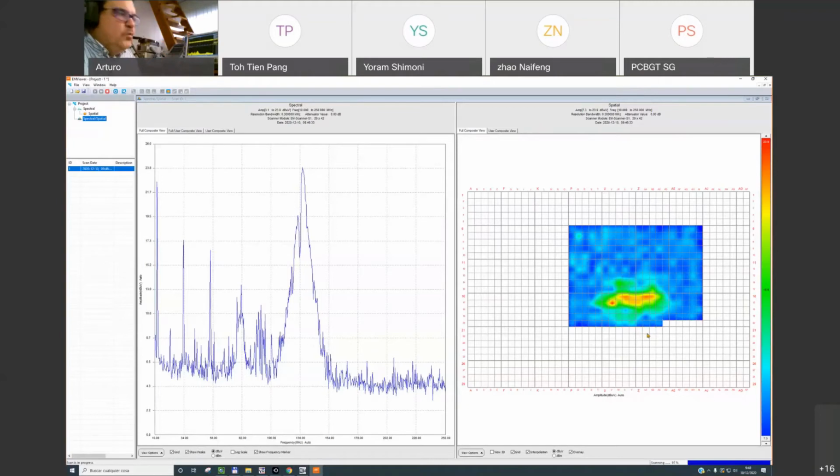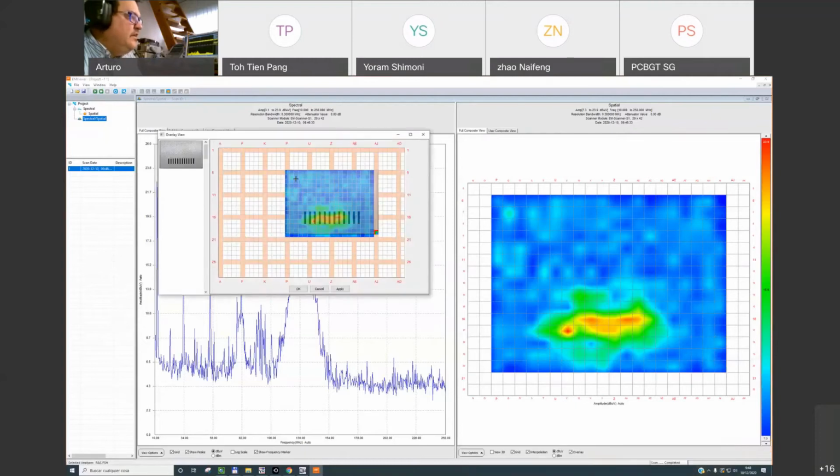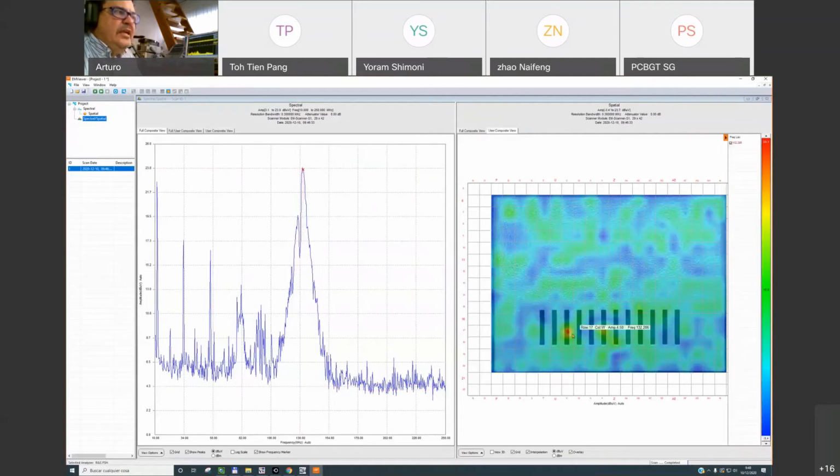So you can see, or we can compare now. We can see this in Zoom, and again, we can introduce the overlay if we want. It's not necessary, but sometimes introducing the overlay makes it easier to understand what's happening in your circuit. So when I click here and ask where this energy is, this 132 megahertz, the system will give you where it is specifically located.